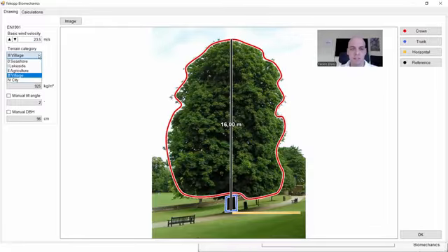After that, you can select the terrain category. These are also detailed in the standard, and I ask you to refer to the standard. As you can see, you have seashore, lakeside, agriculture, village, city. The difference between these is that you are going to have much higher winds on a seashore as you go upwards than in a city or in a village. And I will probably demonstrate this as well.